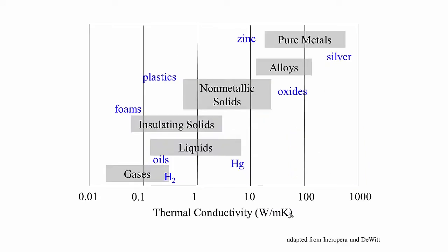Okay, well, now that we've thought about what this thermal conductivity is, a proportionality between the temperature gradient and the heat flux rate, the heat flux vector, it's important to understand values of the thermal conductivity. So as thermal engineers, properties like the thermal conductivity of air are useful. And so the thermal conductivity of air is approximately 0.02 watt per meter Kelvin.